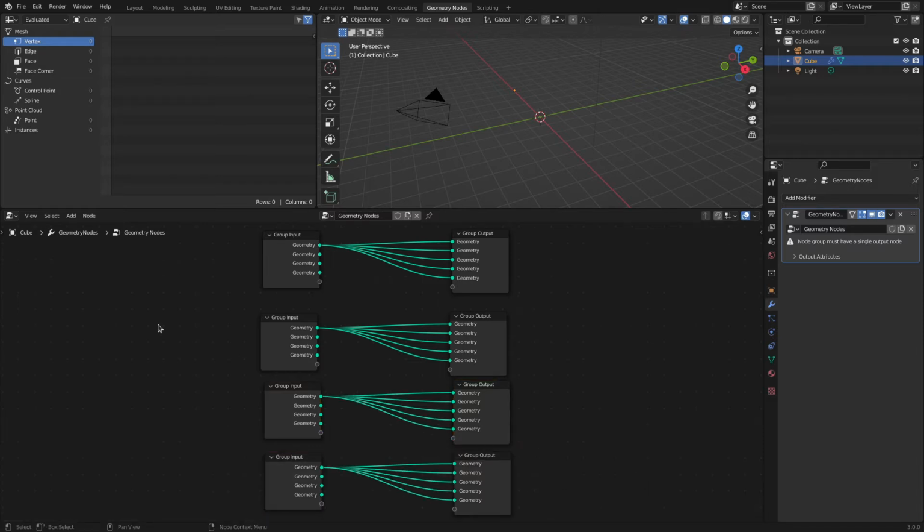Okay. Now if I want to create a link from, let's say, this node down to this guy here, I'm going to hold Shift down and left click to select both of them. If I hit F, nothing's going to happen. I'm not creating any new links. That's why in this case, you're going to want to use make and replace, which is Shift F, not just F. Now I believe you can only do this once.